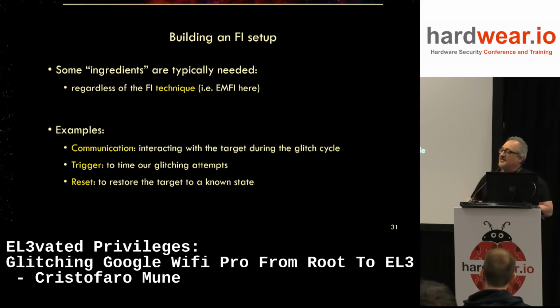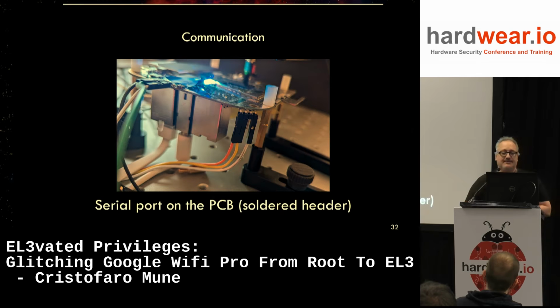And we also would like to reset the device, because in order to make sure that it reboots in a known state. Because if you fault the device and you don't see the effect, that device may be in a faulty state, and you fault on top, and you fault on top, and you fault on top. You may enter into states which can be useful, but are very difficult to decode, understand, and reproduce. So every time we fault the device or do something to the device, and we don't receive the regular response, we reset. Always. In a way that we are always targeting and glitching a known good state to a possible bad state, so that this can be reproduced to a certain extent.